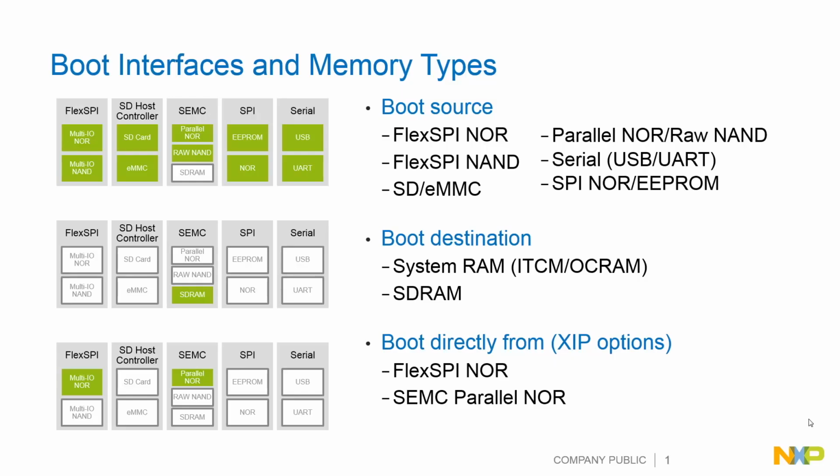I'm a systems engineer here at NXP Semiconductor, and in this video I'm going to talk to you about the i.MX RT boot flow. The RT processors support a number of different boot sources, as shown in the slide here. Most of these boot sources require that the memory be copied from the boot source to a destination memory, either the on-chip system RAM or an external SDRAM.